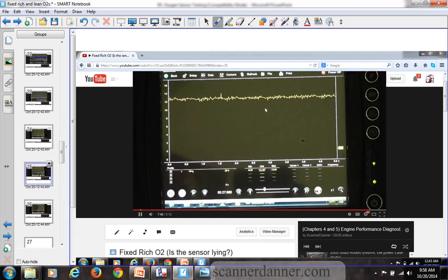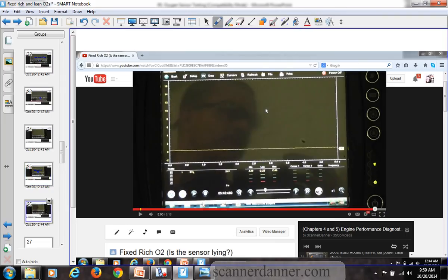This is my O2. This is heater power. How's this one? Car's running. Heater power test. What do we see? This says 1257 down here, 12.57. How's that heater power? That's good. Heater ground, this is 0.37. That's 0.37, that's this number right here.